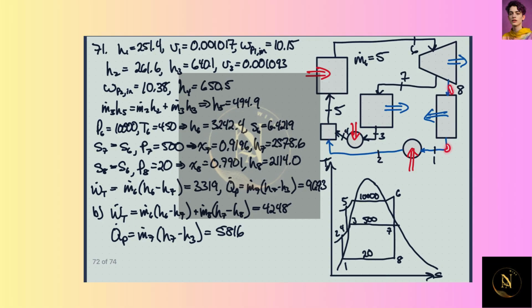So these blue lines are the second mode where we actually need to dump some extra heat that I guess we didn't need for the process heater. So if we don't need all the heat here, we let some of it finish its way through the turbine. And so in that case, we'll get more power out here, but we'll get less heat here. So it's a trade-off, and we'll see that.